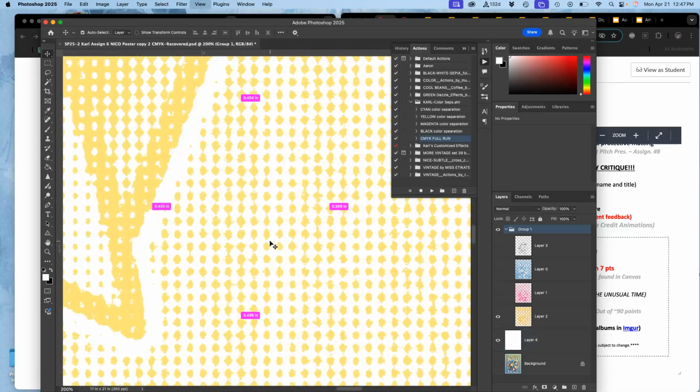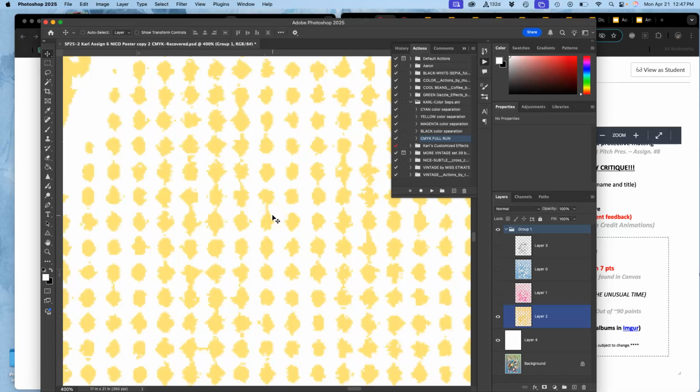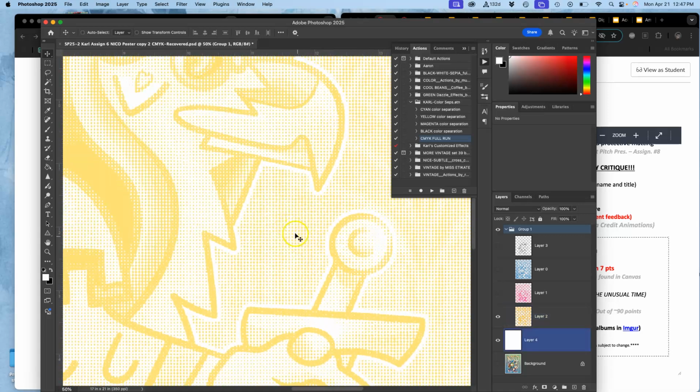These are the yellow inks, but ink can only ever be fully there or fully not there, right? You can't thin it out on a printing press like you can with an ink wash painting. So the way we thin it out is through mechanical separation, through dots. And the angle of those dots for yellow on mechanical reproduction is 0 degrees. Which can also be said as 90 degrees, right? So it's horizontal and vertical. You see how the dots line up? Horizontal and vertical.